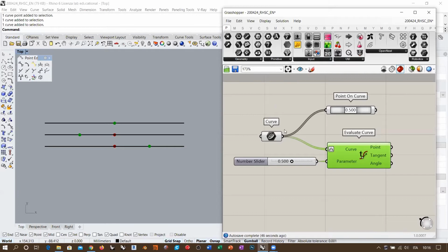Okay, but if we take into account the second curve, you see that the 0.5 parameter corresponds to this value here, to this point here. Why? Because this curve has a denser concentration of control points in the first part. Normally I use a metaphor here: as there are more magnets, the magnets pull the curve strongly. So the curve is basically trapped in this area at the initial part. So the point moves slowly in the first part and moves faster in the second part.